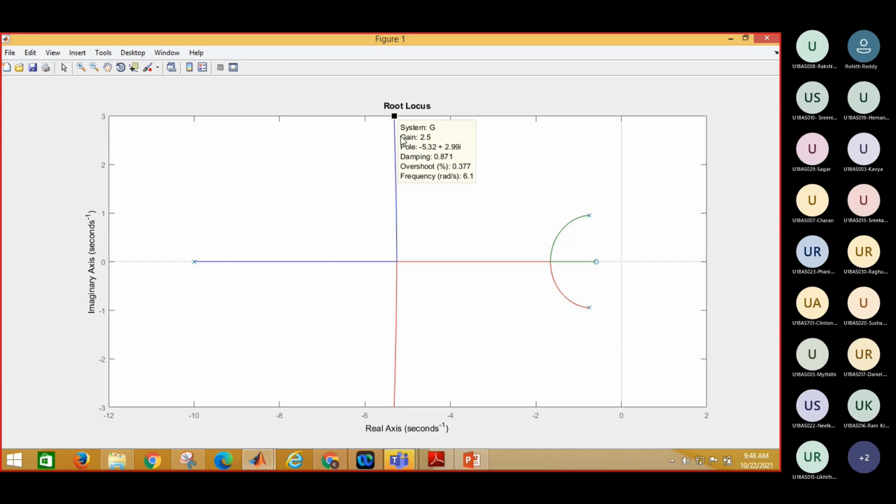So why do we choose a high damping for the inner loop? Suppose you consider the outer loop: the closed outer loop has a tendency to reduce your damping. That's why we select a higher value for the inner loop gain, for higher damping.